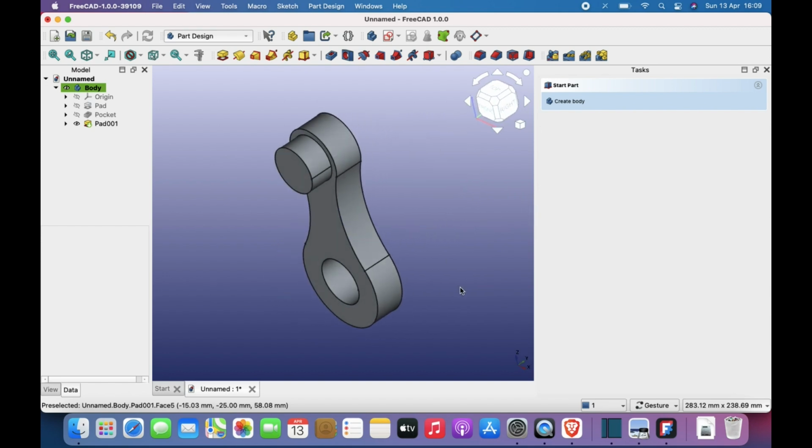Very beautiful object. The reason I made the diameter of this circle dependent on the diameter of this circle is because of something that usually comes up. So for instance, you may submit this design, and in your factory or on the shop floor you may be asked, okay, we need a completely different design, but we want to change the diameter of the hole and the diameter of this circle to both 20 millimeters. Now it's easy to come and change them both one by one, but what if you had like 5-6 different holes that were the same and you want to change all of them? Changing them one by one is obviously not sane, so the best thing is to make them dependent on each other. So let me show you what I mean.